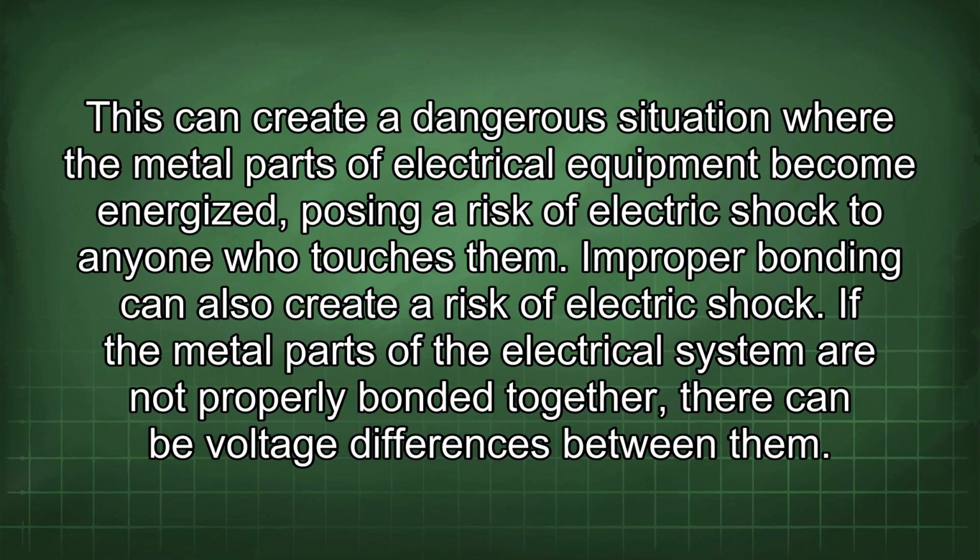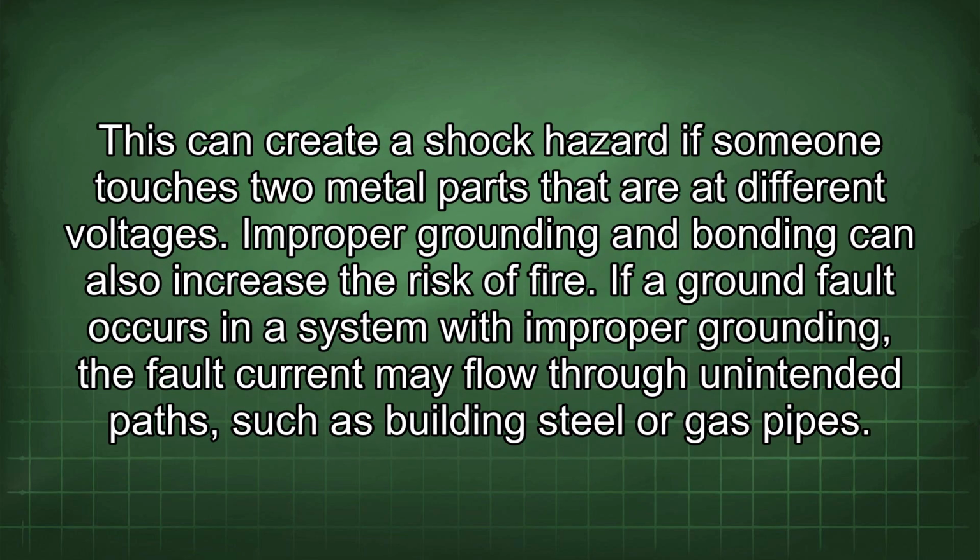Improper bonding can also create a risk of electric shock. If the metal parts of the electrical system are not properly bonded together, there can be voltage differences between them. This can create a shock hazard if someone touches two metal parts that are at different voltages.